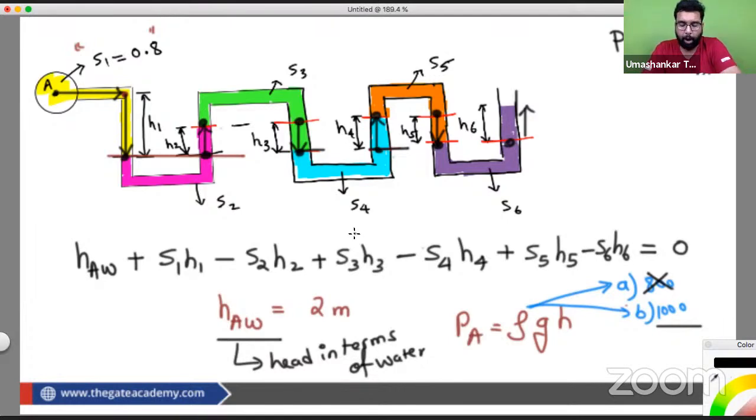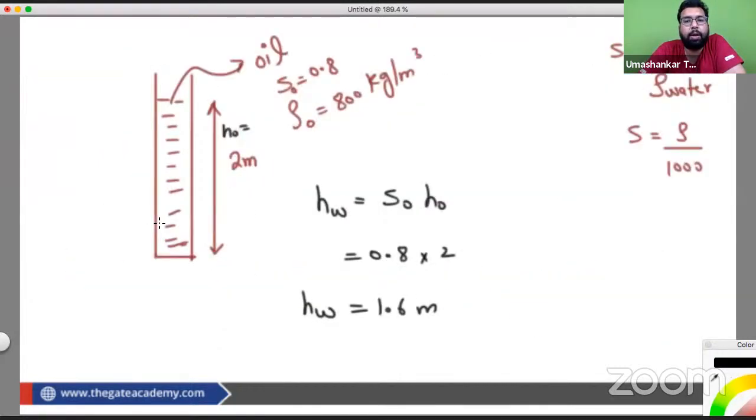Now remember this point, beta. If you are using this method for solving your question, in the last, when you are supposed to change your findings into Pascal or Newton per meter square, you must be multiplying the GH with your density, which is 1000. Now, please answer me if it is fine to you guys or not.